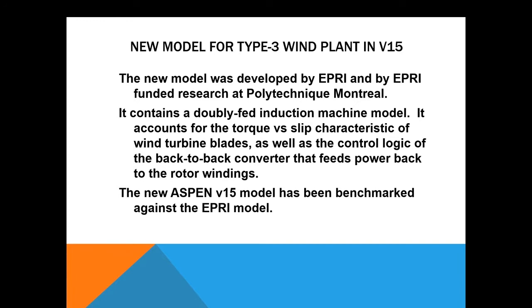This model started out as a dynamic model, then through a little bit of fancy footwork, ASPEN was able to change it to a quasi-steady state model that works with phasors so that it could be used in a short circuit program.